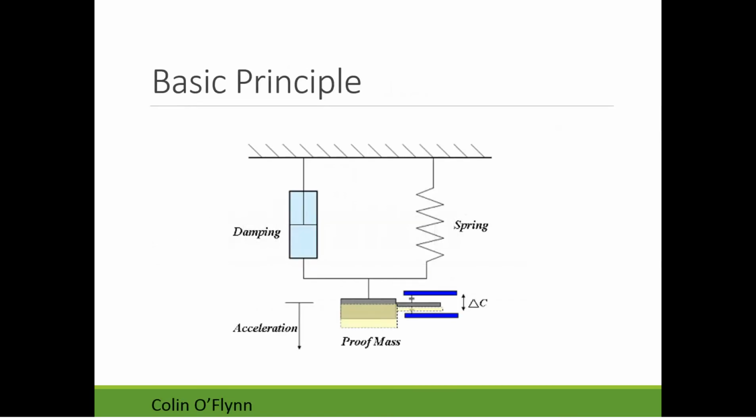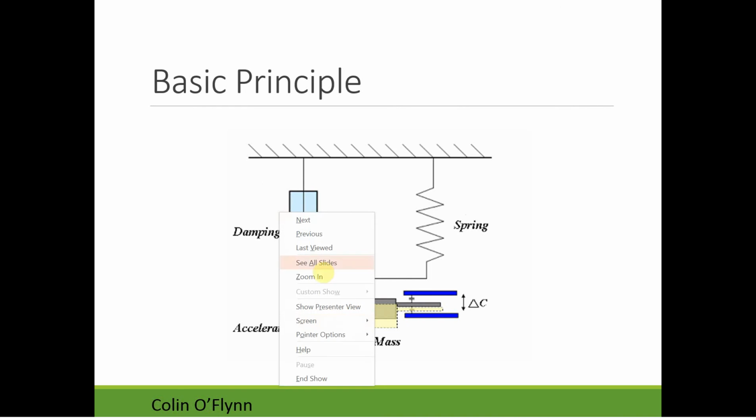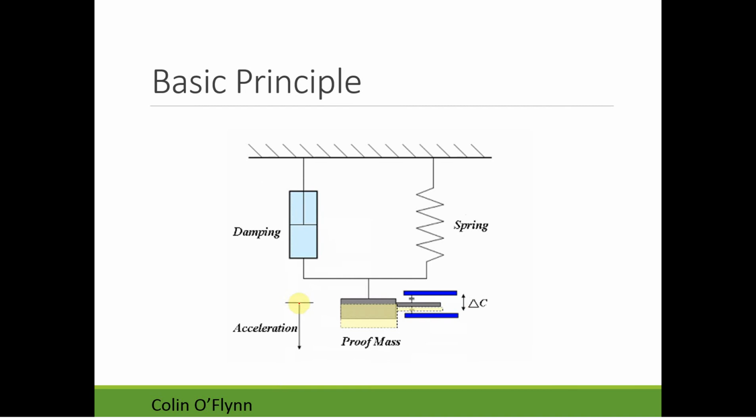Most of the rest of this will be covered in the navigation lecture. Very briefly, there are other detectors, so we can detect actual acceleration, as your robot moves. This used to be done with a mass that would be connected to springs. There are now very small sensors that do effectively the same thing, but you can see we have a mass, and it has a spring that's just keeping it at a constant position.